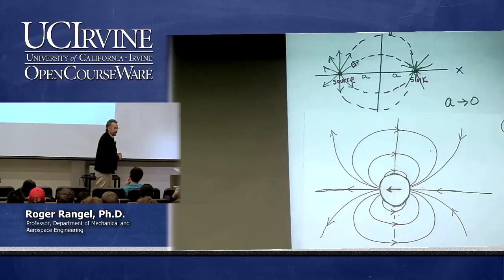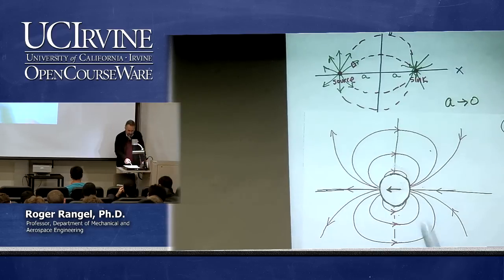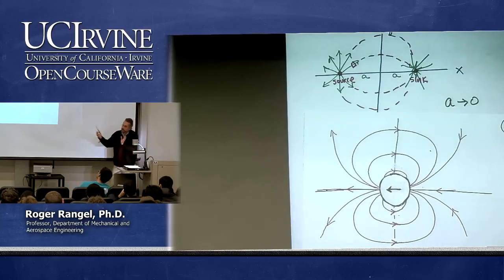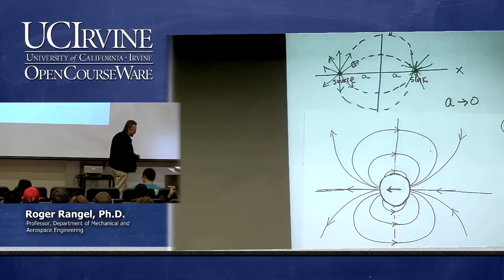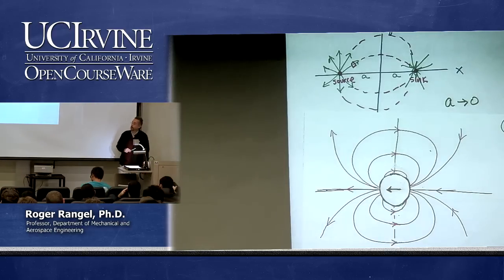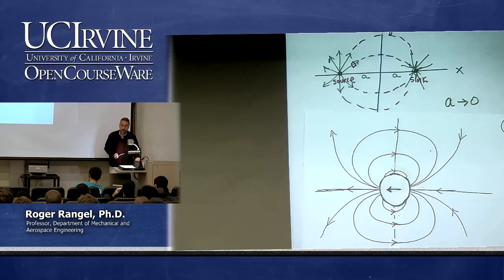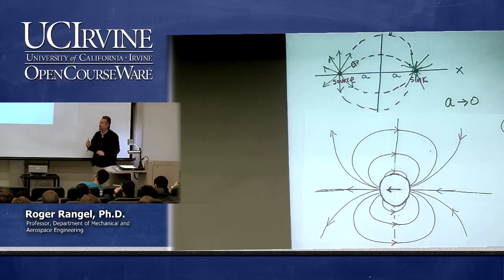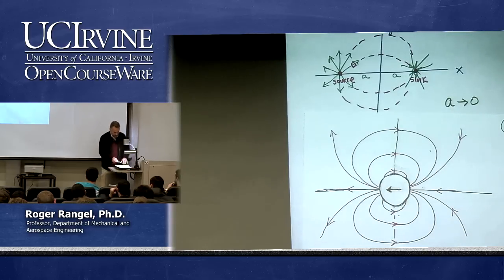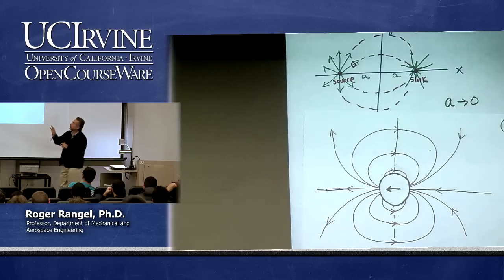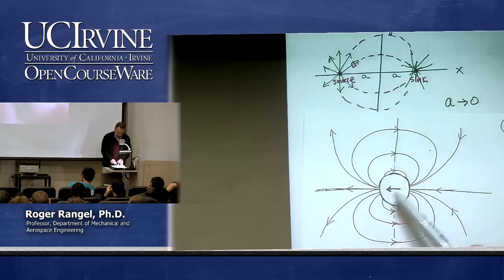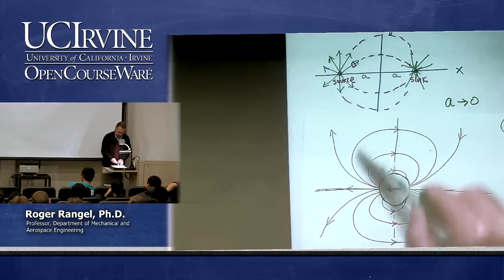So if I have a cylinder, and it's a transient flow, it's an unsteady flow. So this cylinder is moving, is traversing the plane from right to left with a certain constant velocity. And this is what it would look like if I take an instant photograph when it is right at the origin. But remember, this is an unsteady flow. So if this is my cylinder, essentially what it is doing is pushing the fluid ahead of it forward. So as it moves to the left, it's pushing all this fluid out. That's why the streamlines go out like that.